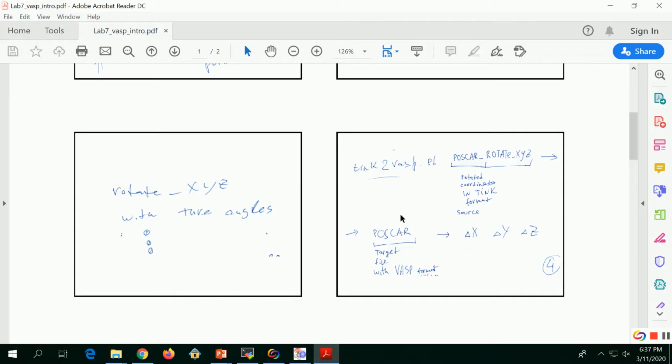These 3 numerical parameters are what we were talking about at the very beginning: the amount of vacuum contributed in each direction for this model. If you are describing only isolated molecules or quantum dots, you just add a liberal amount, like 7 or 10 angstrom, right? But if you have periodicity in, say, the x direction and nothing periodic in the others, then you add a liberal amount of vacuum in the aperiodic dimensions, and give a specific amount of vacuum corresponding approximately to the bond length in the direction where periodicity goes, right?